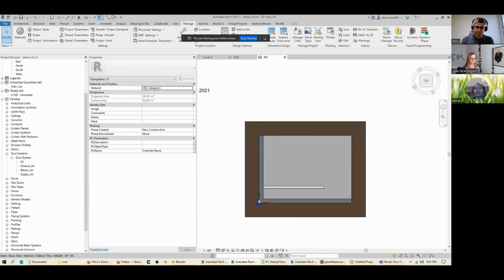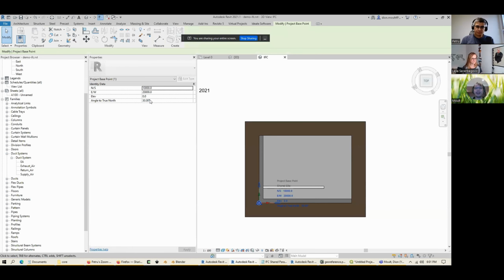So if an architect sees the true north value in there, he should be aware that if he loads up a surveyor's DWG and he's got two norths, something architects like to check on the DWG, which one should he follow? Follow the grid north. He should also know that he shouldn't use this number for solar studies. He should use a slightly different number for solar studies, and he can ask that from the surveyor. He can say, hey, can you give me the true north sampled at this easting and northing?